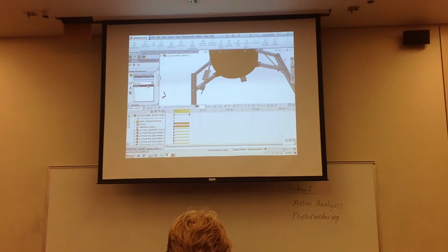Well, that's if you're working with a linear spring that has a coefficient and an exponent of 1. But in SolidWorks, you can define much more complicated springs. Okay? You can do nonlinear springs. For now, we'll just stick with linear. We'll give it a K value. Again, that's the spring constant, how many pounds of force it will produce with a given increment of displacement or deformation. So this is 1 pound per inch.